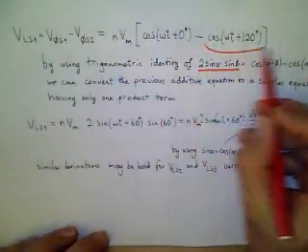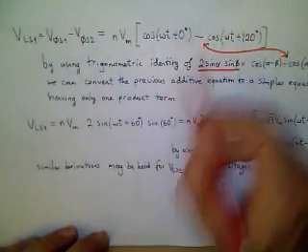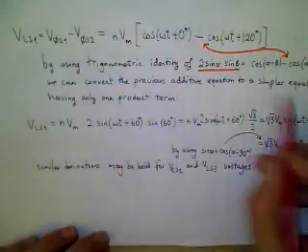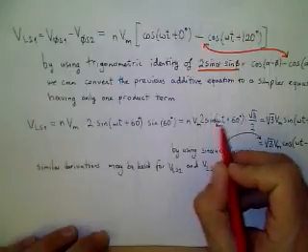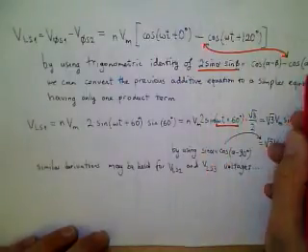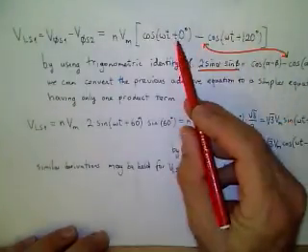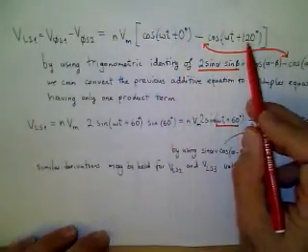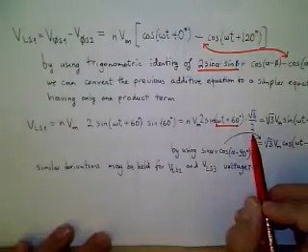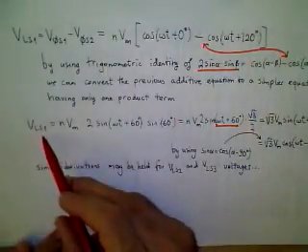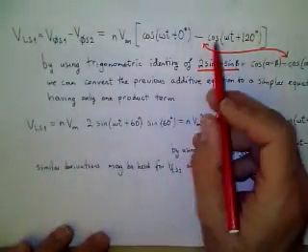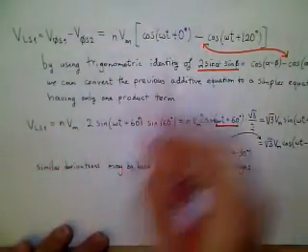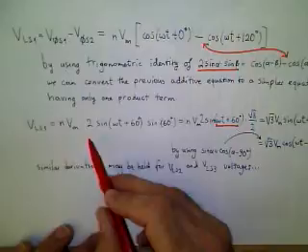So this is very similar to that side. Alpha and beta can be defined: alpha is omega t plus 60, beta is 60. So alpha minus beta is angle 0, and alpha plus beta is angle 120 degrees. If you rewrite by using this equation, the line voltage is simplified. The subtraction of the cosines is eliminated.